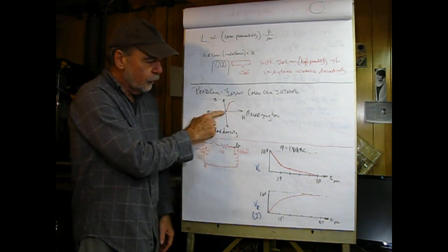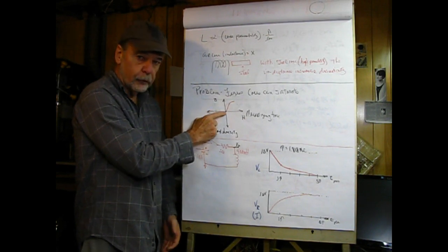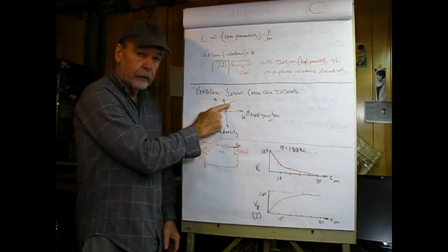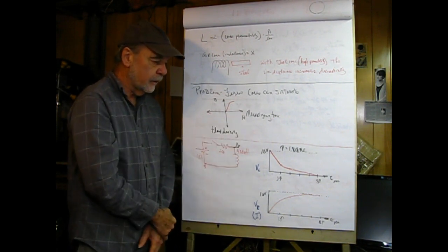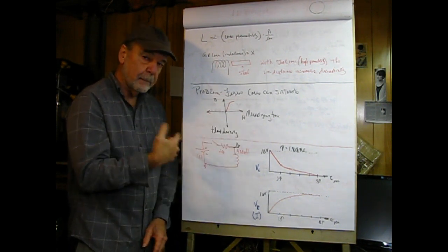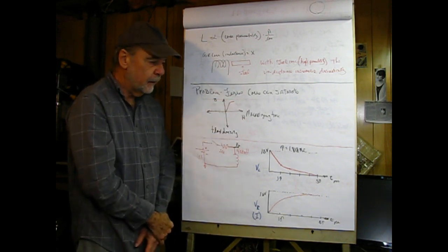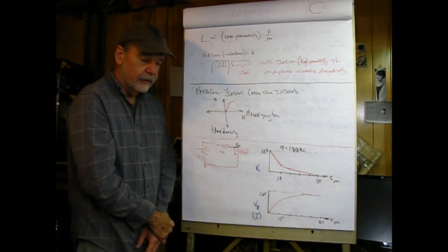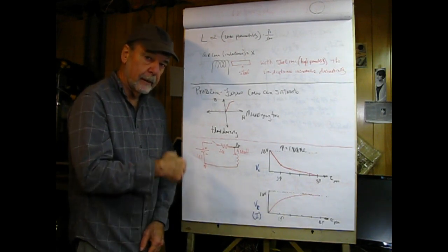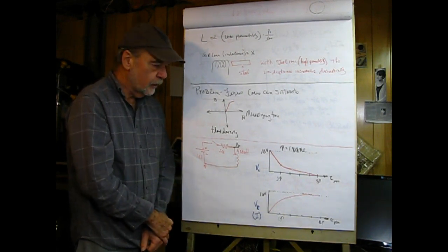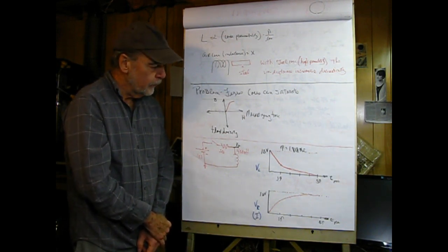As we see, as current starts to flow through the coil, the flux per unit area builds linearly, and then it reaches a point where increases in the magnetizing force will not produce corresponding increases in the flux density. And that's called saturation. It's a nonlinear effect, and depending upon the application, it could be a bad situation. Generally speaking, you do not want things to saturate.